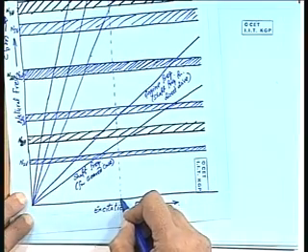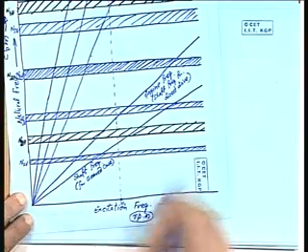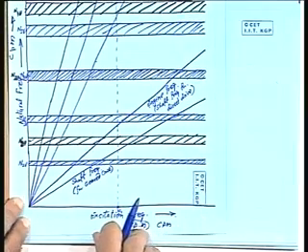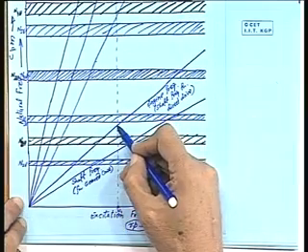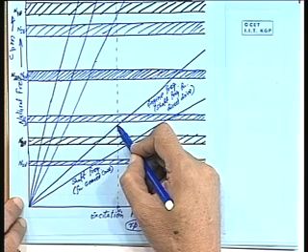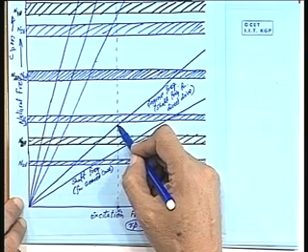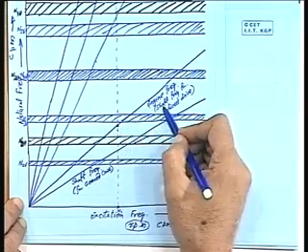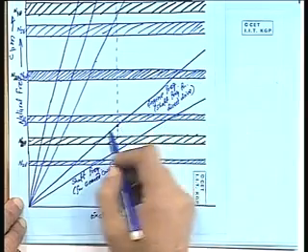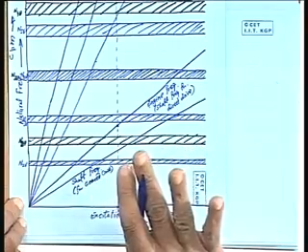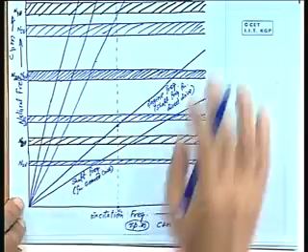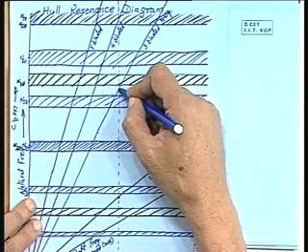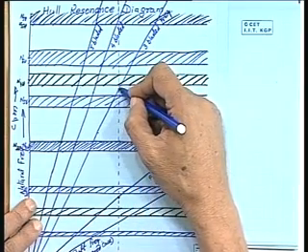You see, this is the RPM. When this engine is in operation, it will have this RPM as excitation, and if it is direct drive, this is the shaft RPM also. So, as far as the engine frequency and the shaft frequency are concerned, it is in the clear zone, not in the banded part. If it comes in the hatched part, it is not to be accepted. If you come to this point here, it is clear of the 3-bladed frequency.